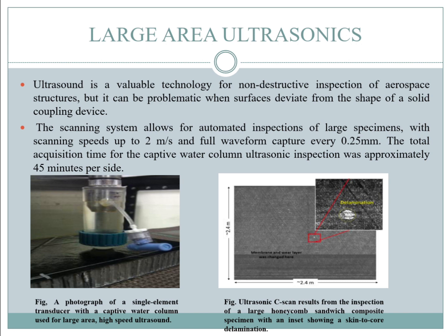The scanning system allows for the automated inspection of large specimens with scanning speeds up to 2 meters per second and full waveform capture every 0.25 mm. The total acquisition time for the captive water column ultrasonic inspection was approximately 45 minutes per site.